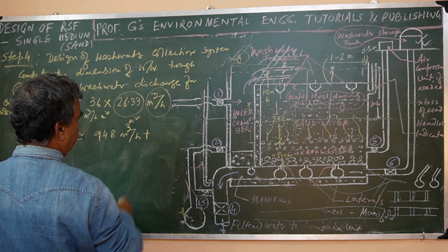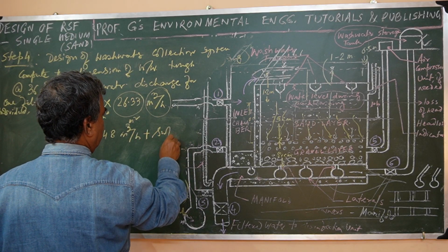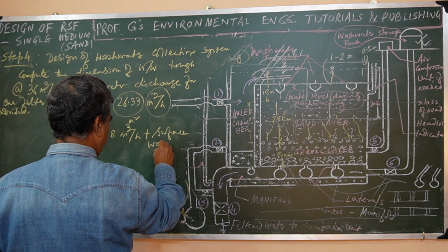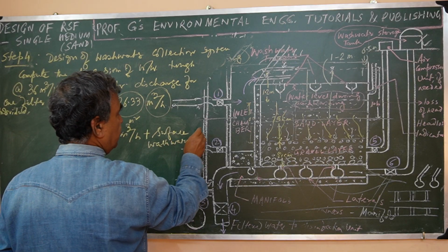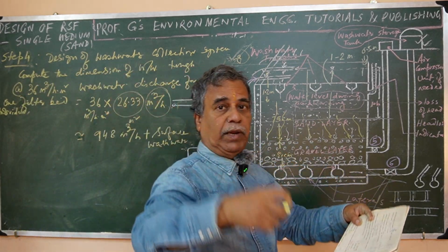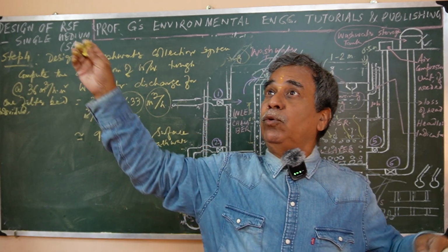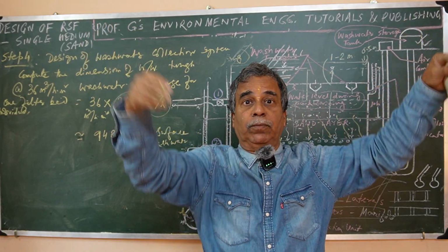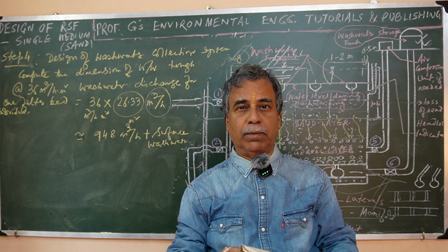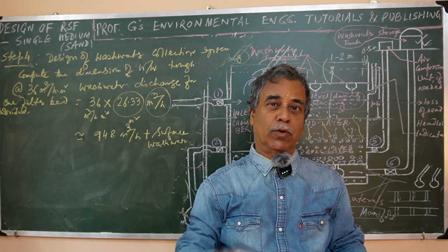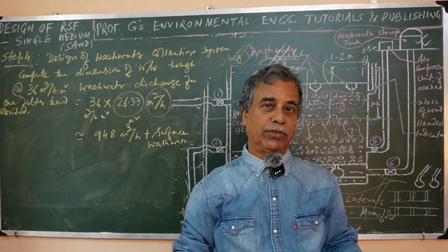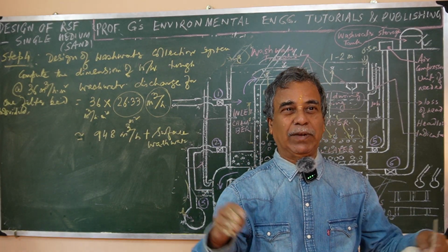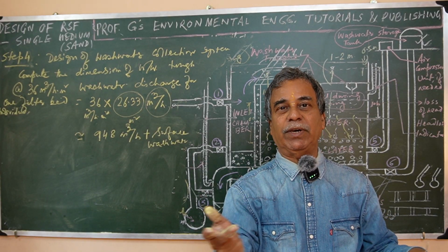To that, sometimes what we do, if we use water for clearing the surface, I explained that, right? Suppose this is a filter box, so at the upper end we have provided the jet sometimes to break the clay patch or mud ball formed on the surface of the filter bed, or to clear the clay patch which otherwise is not being cleared.